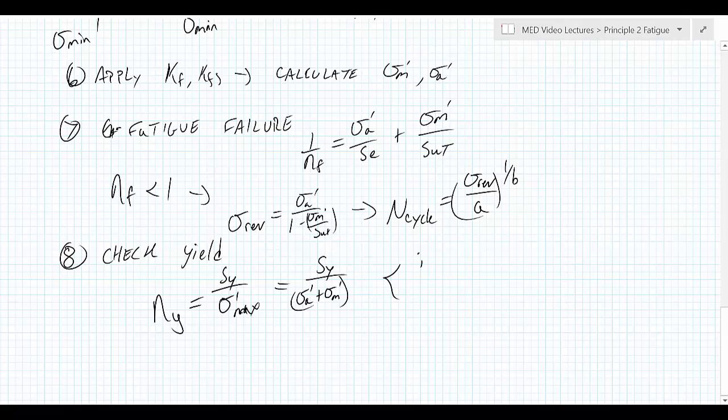And note, this includes stress concentration factors. And when we did yield stress, we said don't use stress concentration factors. Well, it increases the value of the stress higher than it really is. And so the problem here is that you're underestimating the strength of your part. You're overestimating the stress. And so the way that this is wrong is conservative.